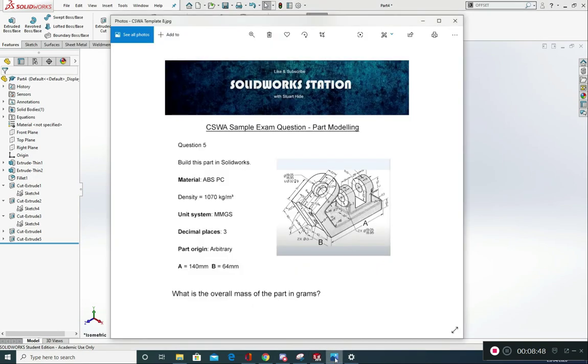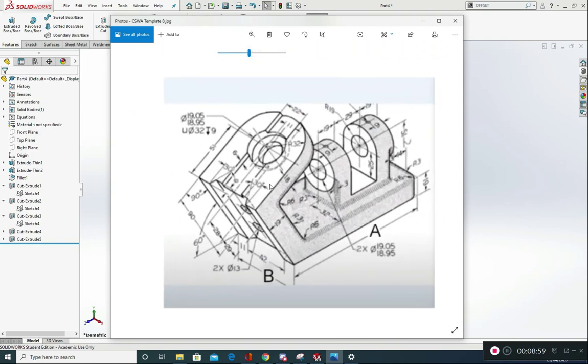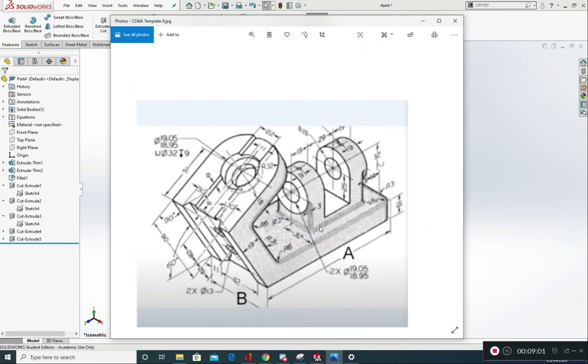Okay, so the next thing that I'm going to look at is producing this last bit here. In order to do that, I'm going to have to create a new reference plane. Now we're going to have to do a little bit of adding up here, dividing, in order to get the right location for the reference plane to sit. So I'm going to use this 19, this 29 and this 19. I'm going to add those together to give me 67.